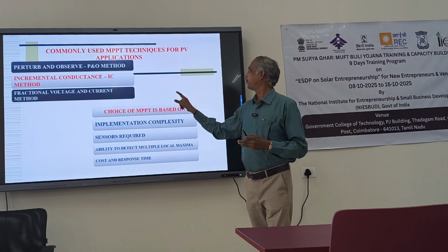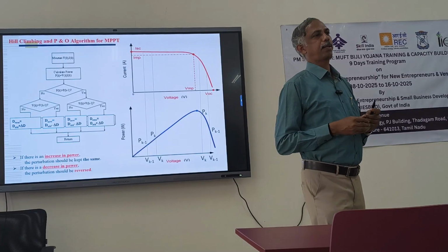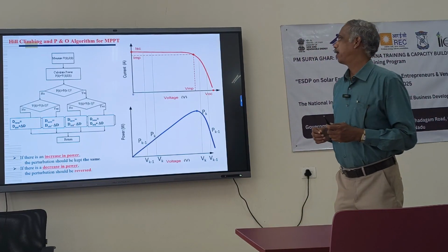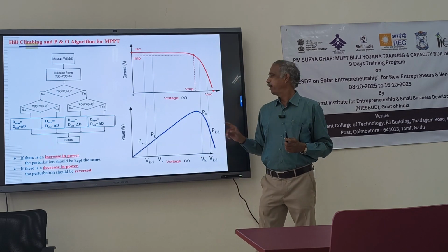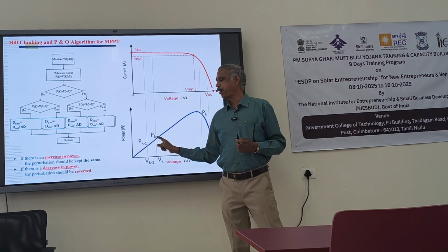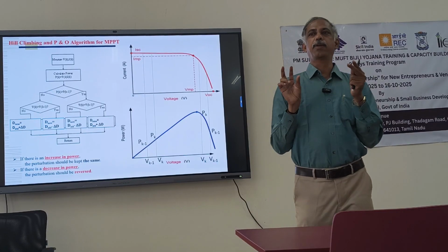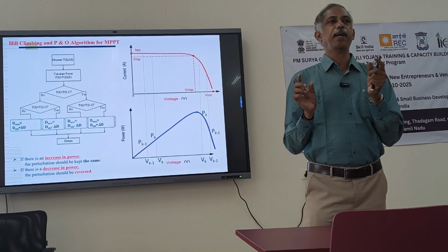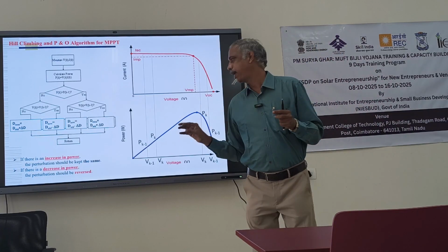Okay. First one, the MPPT algorithm or hill climbing algorithm, whose other name is the perturb and observe method. This is how we track the maximum power point, bringing the operating point there. First, they will calculate the power. They will sense the voltage and current using two sensors and multiply them. Then they get the power, which we take as the actual power, Pk.